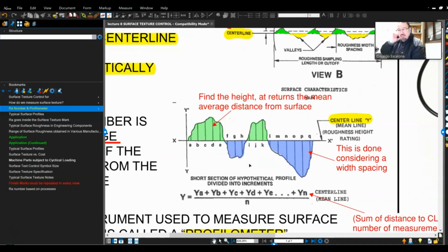So let me tell you what the profilometer is doing. The profilometer looks at the tops and it looks at the bottoms. Let's call them the peaks and the valleys, the summits and the valleys. And it tries to calculate, and actually calculates, a mean line. Let's call it a center line. That's all done internally, you don't have to do anything. It creates a center line somewhere in the middle, depending on these tops and bottoms that it finds as it went from one side to the other.